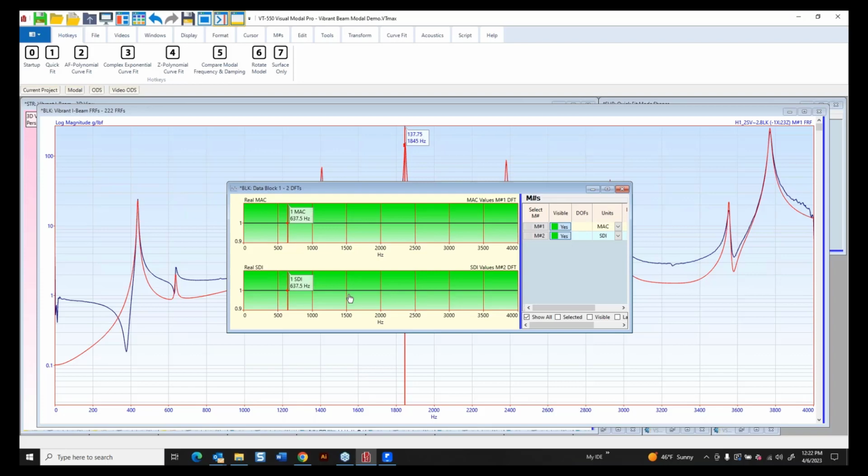Linearity: all of modal analysis is based on what's called linear dynamic motion. And that goes back to the differential equations, Newton's second law, F equals ma. That's a linear equation that involves force and acceleration. Now, does the real world behave linearly? Not always.